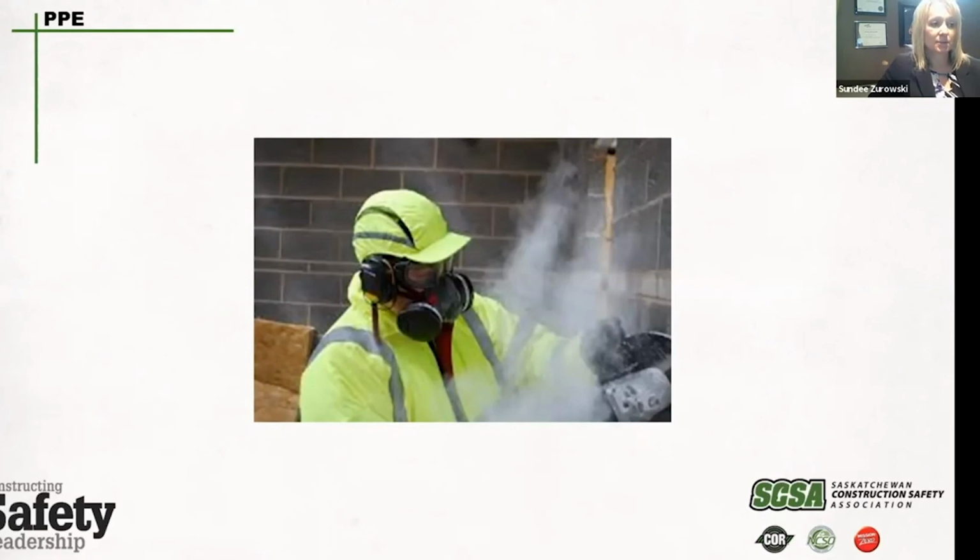In addition to respiratory protection, workers need to be provided with appropriate protective clothing at the work site. This is done to make sure that street clothes are not contaminated with silica. Your eyes should be protected to prevent the silica particles from entering them, causing irritation or damage. Work practices can be implemented to reduce potential exposures.